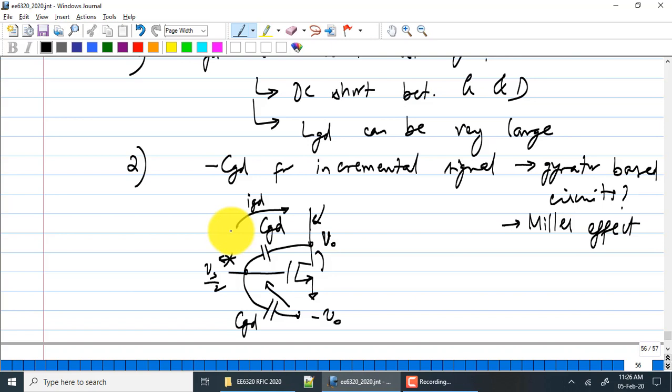Okay. So such circuits, how do you create minus VO? If you had a differential circuit, you already have ready access to minus VO. Okay, and it turns out that this technique is most useful when you have differential circuits. Okay, so this technique is called capacitive neutralization. Okay, removing the effect of the parasitic capacitance through another capacitance.